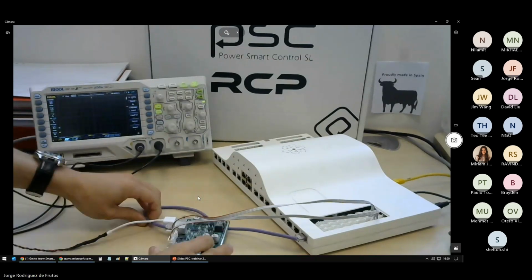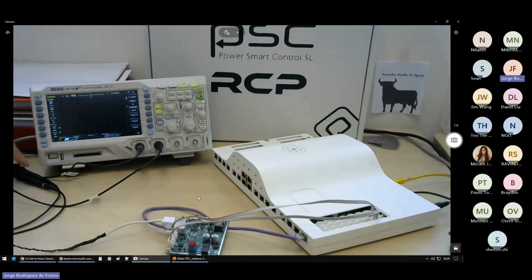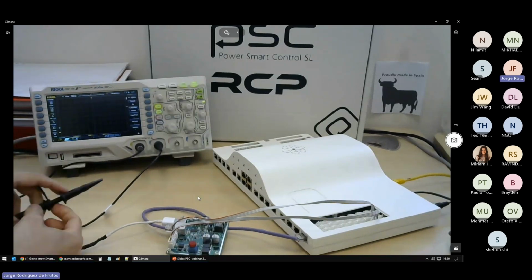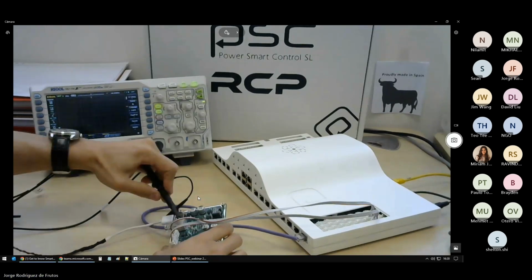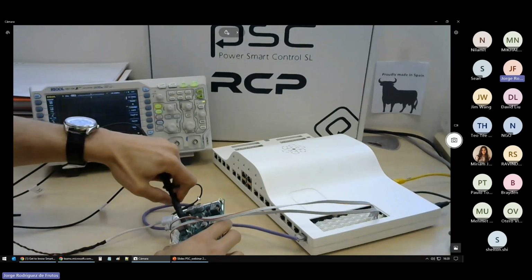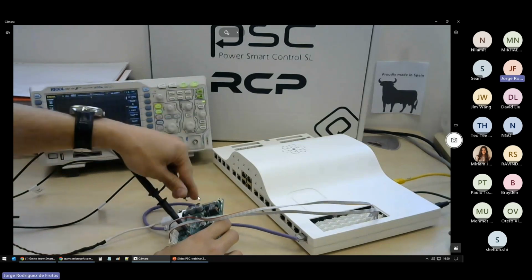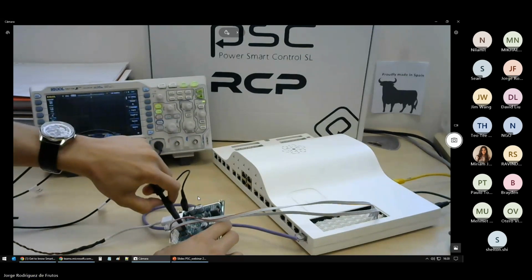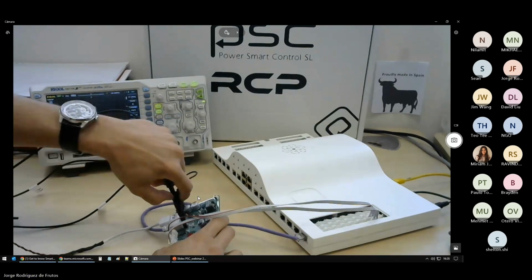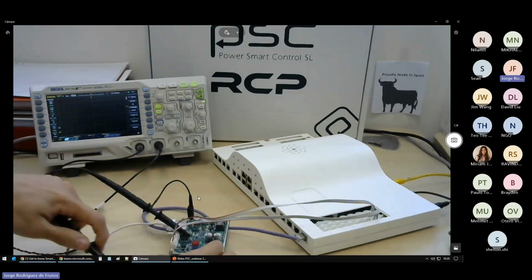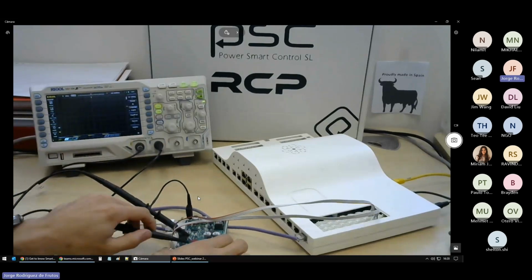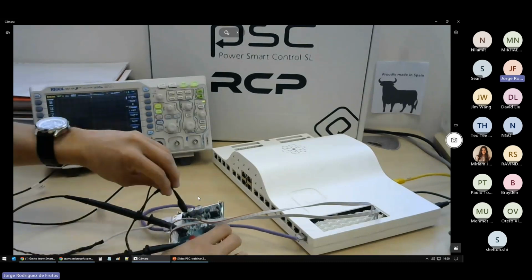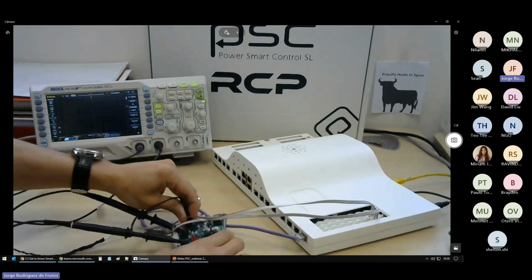And now I am going to connect the oscilloscope probes, which will be in the inductor current test point in here, with the ground connected in this test point. Sorry, it jumps. And the very same with the output voltage. So I'm going to connect it here, yes. And the extra ground test point is in here, yes.